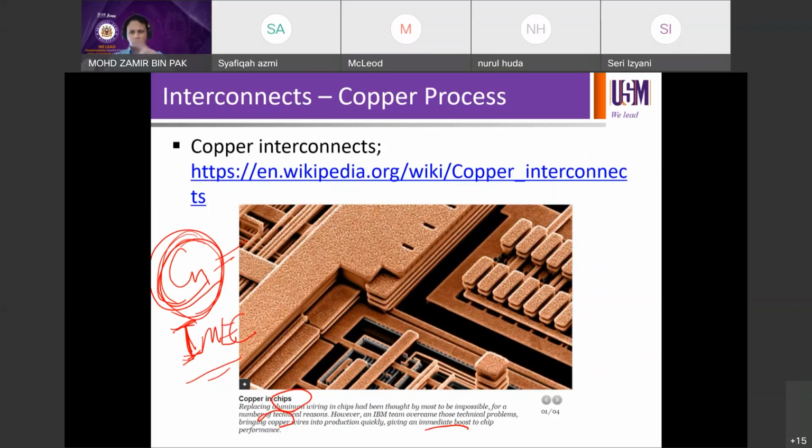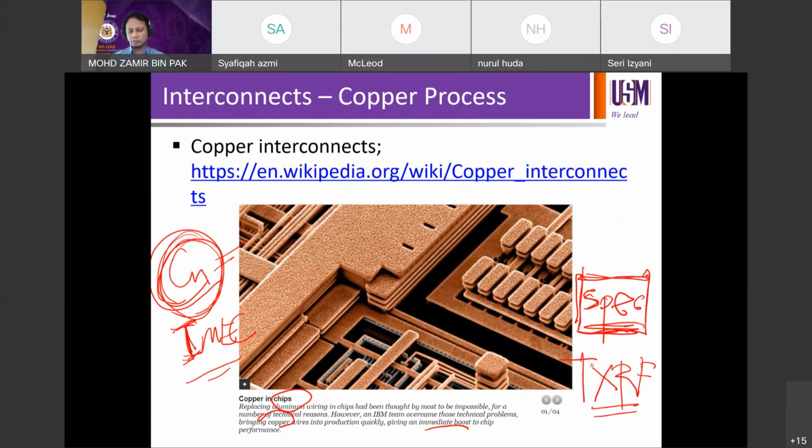Okay, you switch from copper to another, there has to be a downtime and verification to make sure that the copper left in the equipment, on the robots and everything is below the threshold level, below the spec limit, right? Well, more than that or close to that, you cannot release the equipment or the process to run conventional technology or non-copper technologies. Okay, gonna verify, right? Sometimes you did the cleaning and then you ran the XRF. The XRF was used, total X-ray fluorescence characterization, to check for the metal contaminants, the level, sensitivities, and the rest.